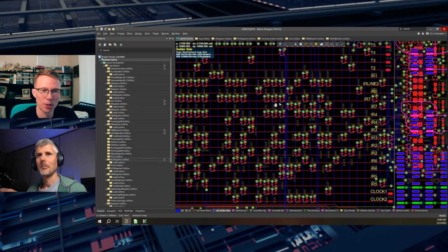As it turns out, that was a good thing, because of some issues with the clock. I discovered that it was possible to get conflicting states in part of the logic. There was one spot where there were 8 super buffers that could actually turn on at the same time, and you'd get a shoot-through current. But because I had a current limited supply, I could see that the current was very, very high.